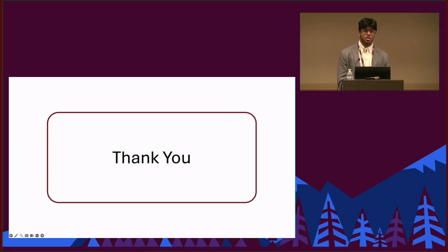The whole flight is being logged onto the flight controller as sort of a black box, I would say. So even if the drone crashed or the battery disconnected, everything's being logged to that flight controller. So then we can easily reference the black box to get the last location, and then it'll resume the mission from that point. Okay, cool.